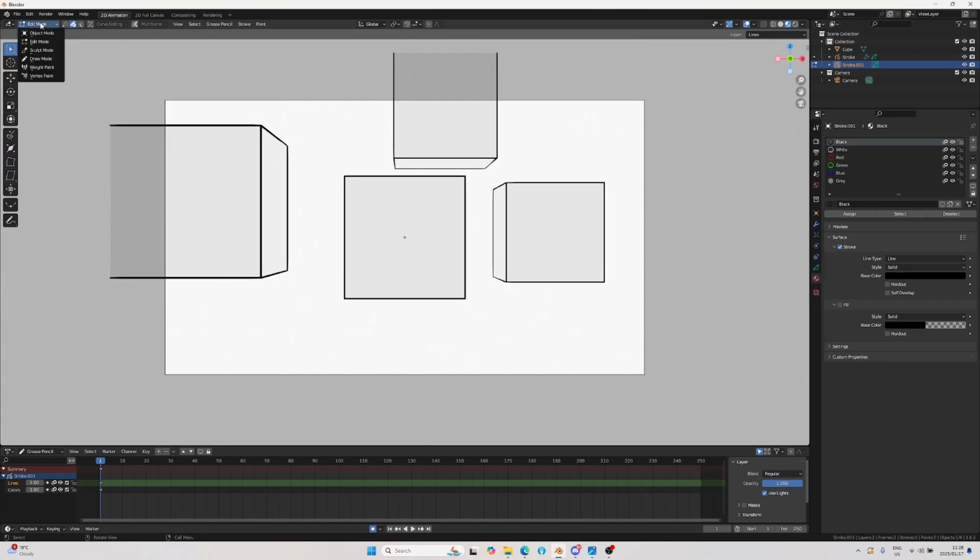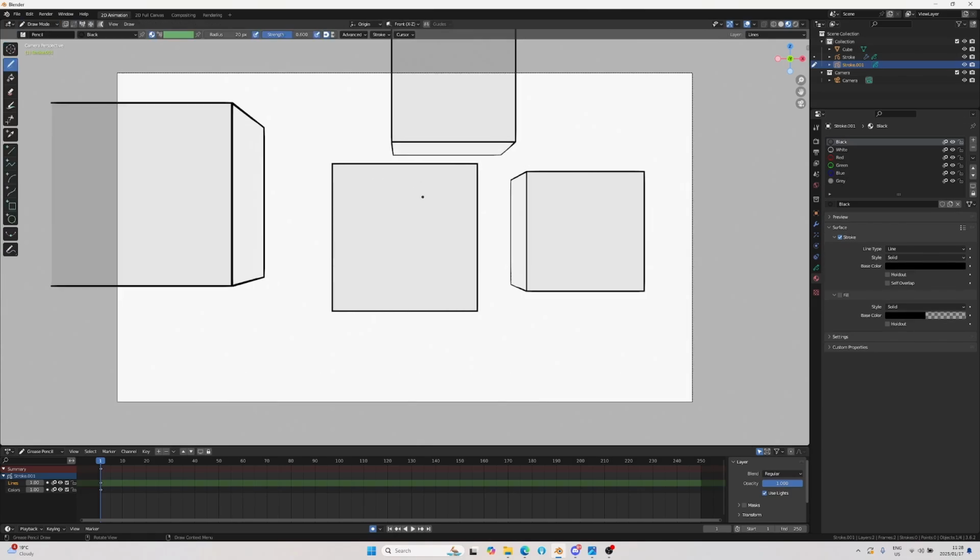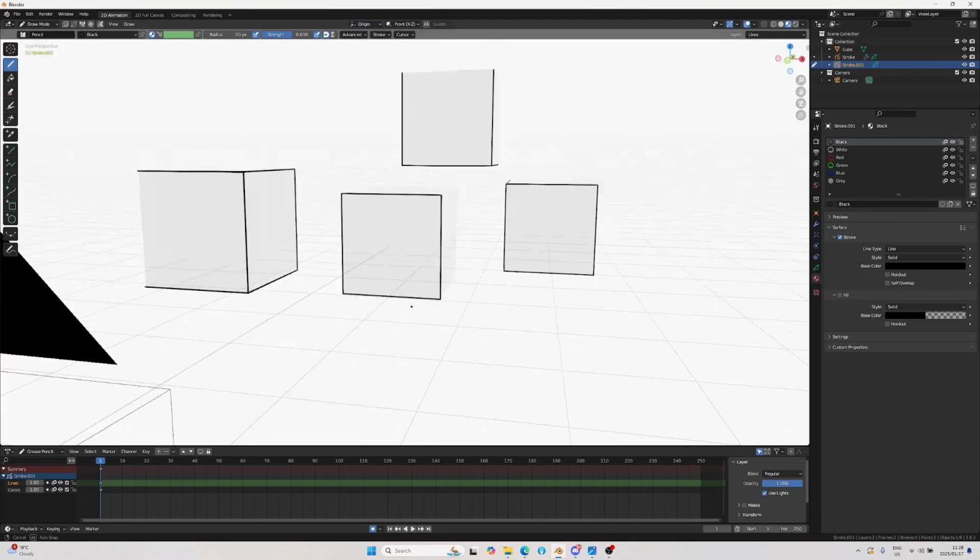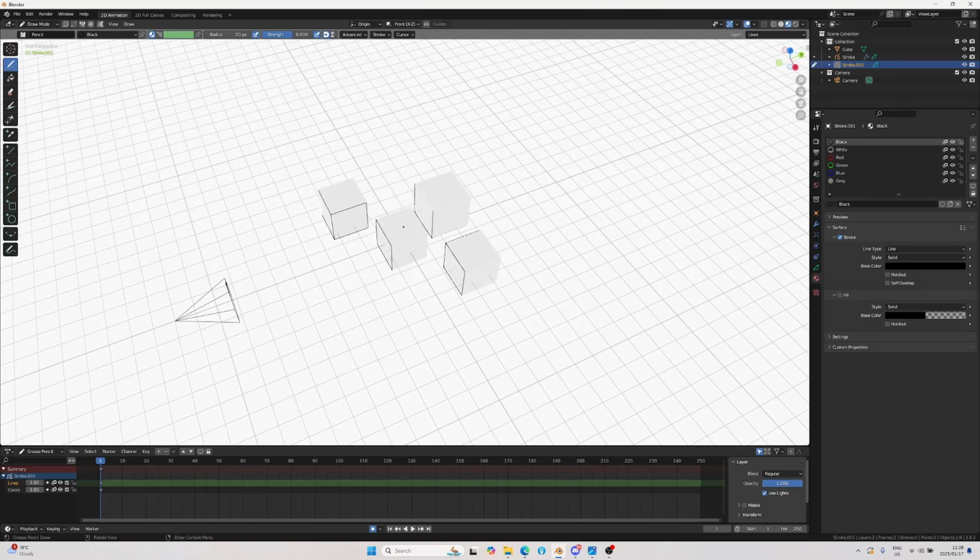Yeah. So if I'm in draw mode in my new stroke, this is another powerful aspect of the Blender Grease Pencil, is you can choose where in 3D space you're drawing onto. By default, it's origin, so you're just going to be drawing at 0, 0 in the world space.